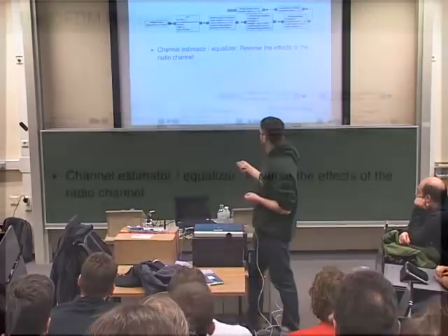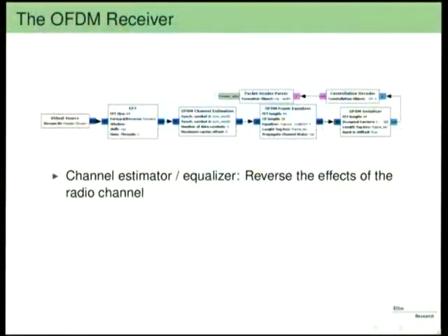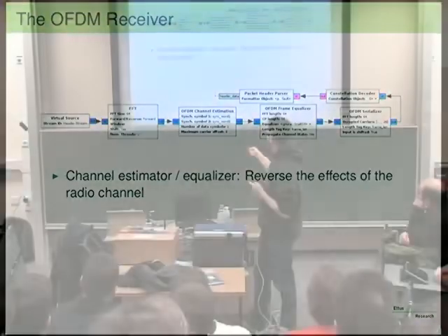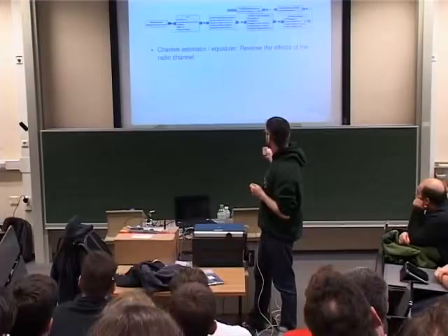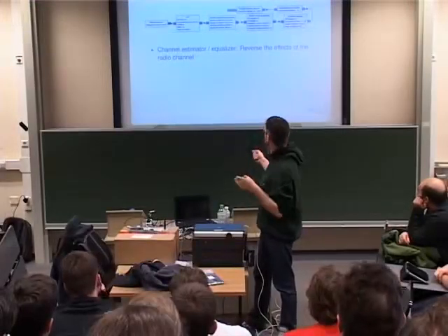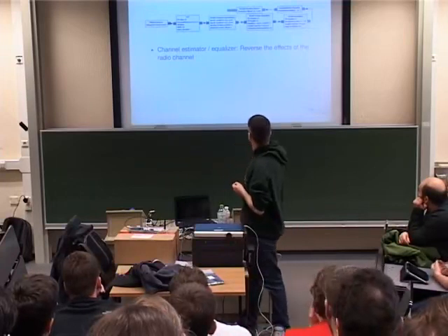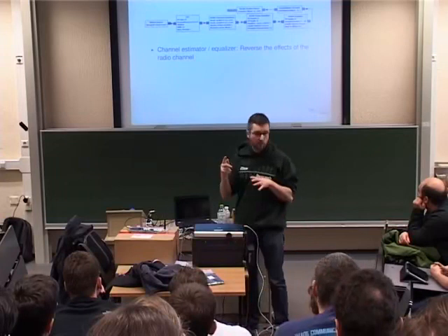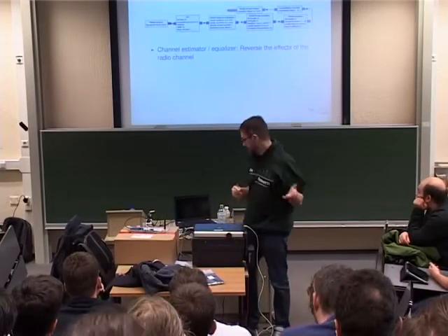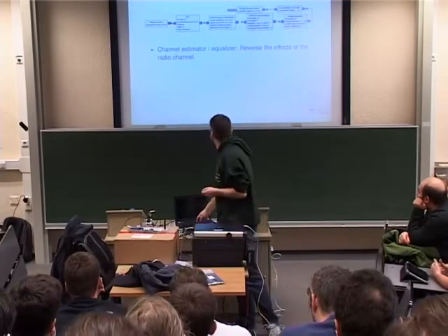Okay, so when we get the header, which is always a fixed length, I mean, anything else wouldn't make sense. And even if you had variable header length, then you could just take the first part of the header to figure out the rest, and then do the same thing twice. And then you just go through the inverse steps of an OFDM receiver. And I don't want to go into the details because it's pretty much the same as before, except we have to figure out how the channel modified the transmit signal, so equalization, estimation.